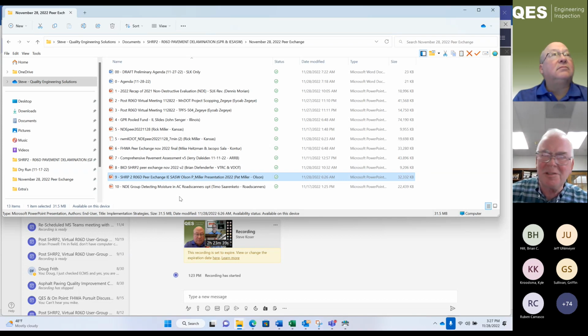This is Larry Olson. I was just going to add to Ian's question that it's important to note that the surface wave method and impact echo don't require the stripping or raveling to be filled with water. It's sensitive to modulus. So it might be a reason to do a little more testing with it, even just for where you're concerned that the conditions weren't ideal for radar. I see. Thank you. Thank you, Larry.